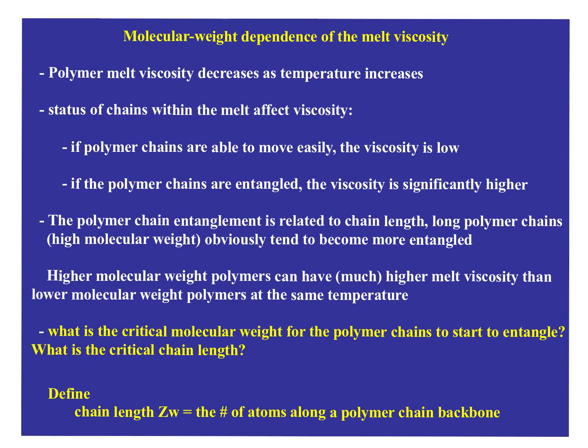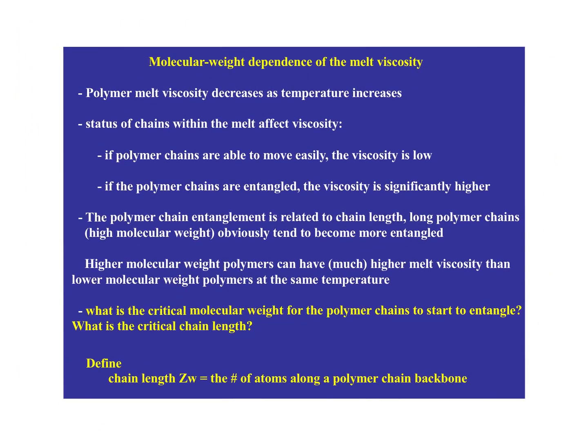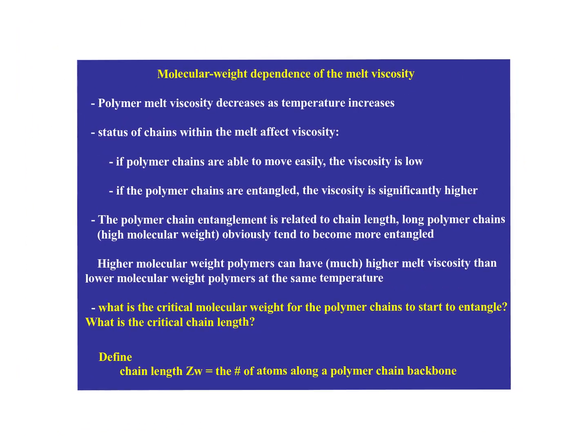Okay, so more information. We talked about it a little bit once or twice, when we were talking about branched polymer chains. But in the context of melt viscosity, as you just had an example of, viscosity decreases as temperature increases, and the status of the chains within that melt will affect the viscosity. And the topic at hand here involves molecular weight. And so you should already know that as we increase molecular weight, viscosity goes up. As we decrease molecular weight, the viscosity goes down.